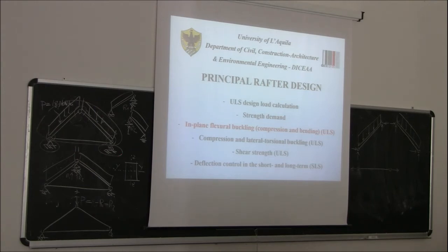So if we talk about in-plane, in-plane means in the plane of the structure. So it will be around Y, okay? Buckling around Y means that this beam is going to deflect vertically, so it will deflect in the plane of the structure. So this will be in-plane buckling, quindi stabilità nel piano, instabilità nel piano. And then we have to check also out of plane, which means around Z in some way. So buckling outside of the plane, okay? So, in-plane flexural buckling.